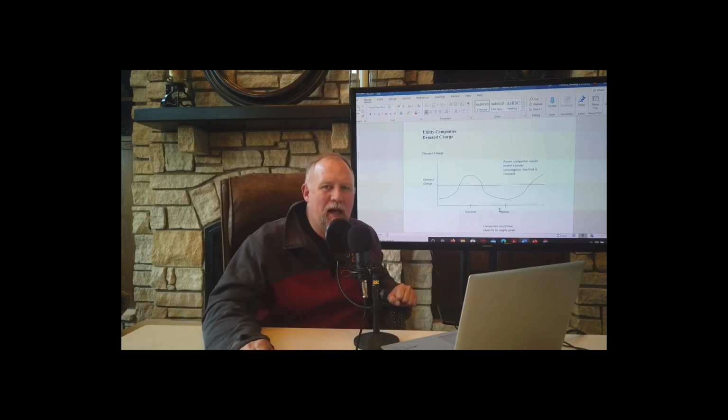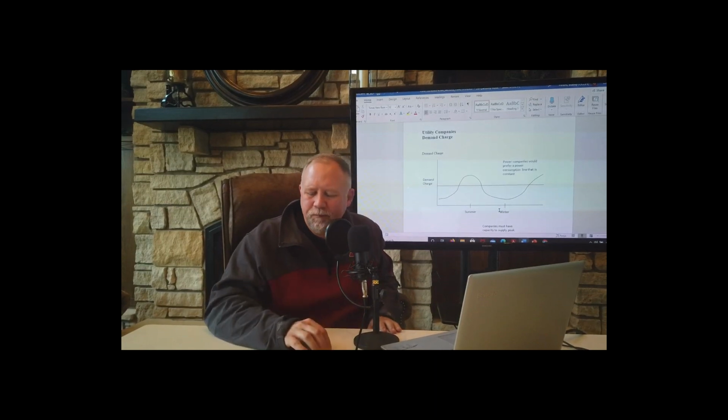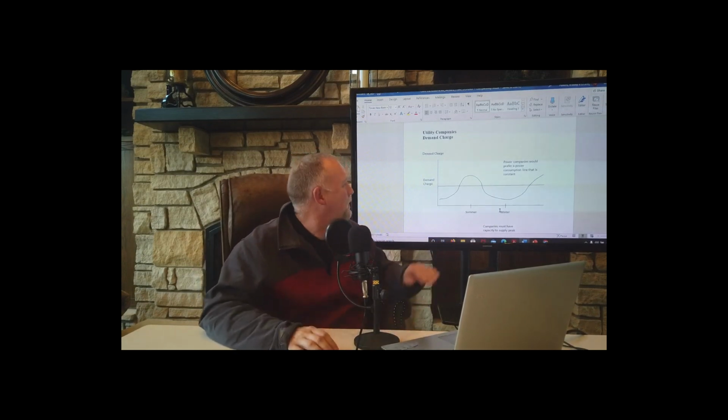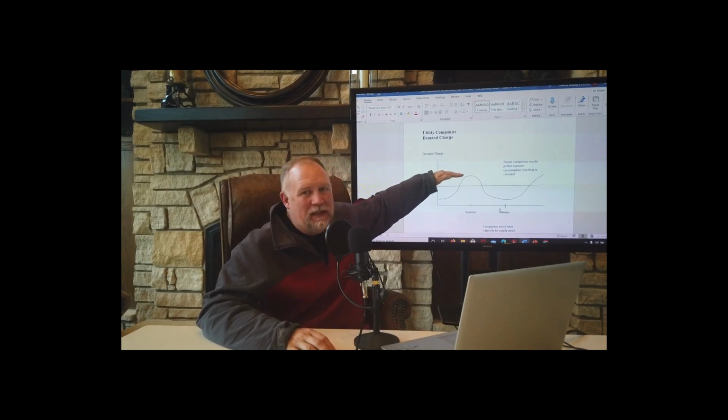And a lot of times they'll monitor the consumption by individual customers in 15-minute increments and try to find out what their peak demand was for the whole month, and then hit them with a demand charge based on that peak. A demand charge is the price that a customer pays to have all this infrastructure in place to hit this maximum demand.